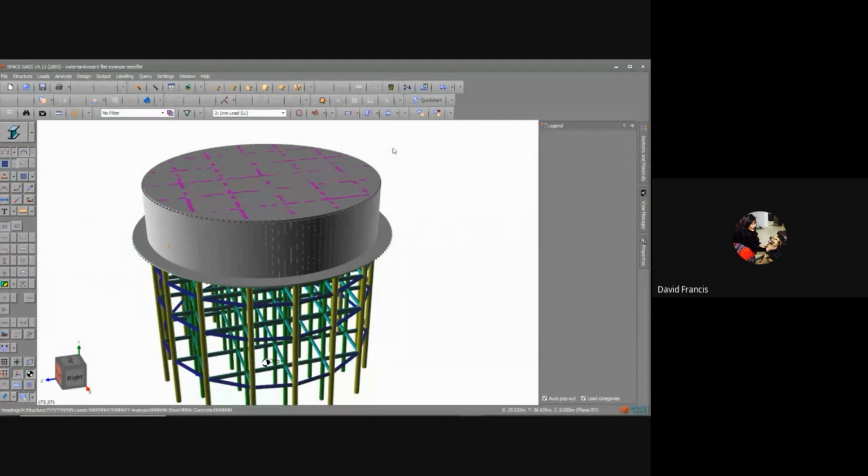So the seismic is a seismic equivalent that comes from 1893, and we haven't done a spectral analysis, but depending if the period exceeds 1 second, I think is a requirement, then we have to do spectral as well. We're not doing that today, but we'll most likely be doing that tomorrow on the workshop session.